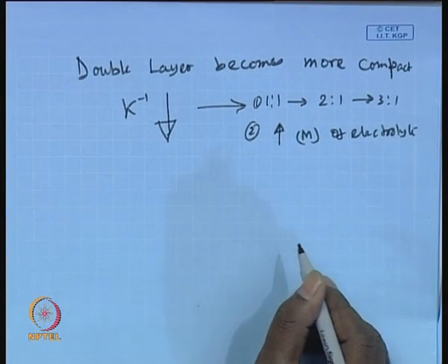So, this gives a typical calculation of the order of magnitude of the Debye length for a typical concentration of electrolyte. Why have I taken 0.01 molar NaCl solution? Because when you talk about the filtration of protein solutions, they typically contain 0.01 molar NaCl as a preservative. So, all protein solutions have electrolytes present, typically 0.01 molar, 0.15 molar, like that. That is why I have taken those values.